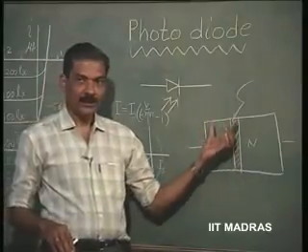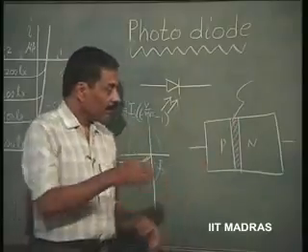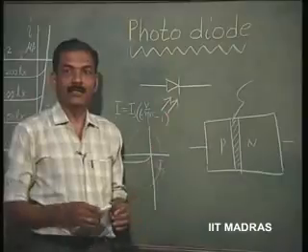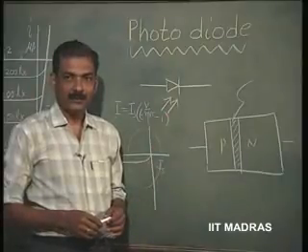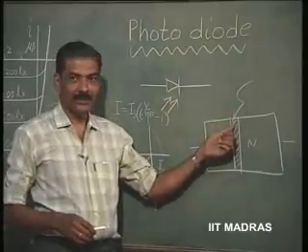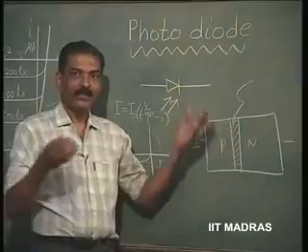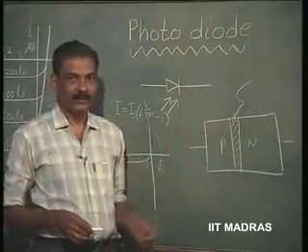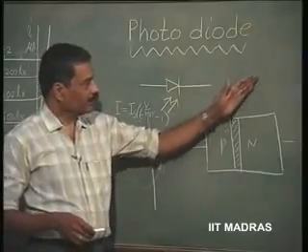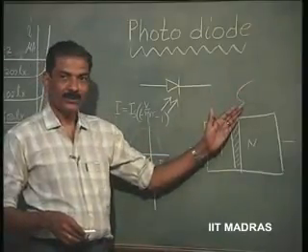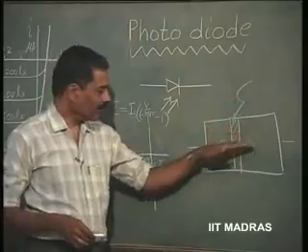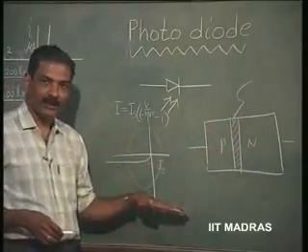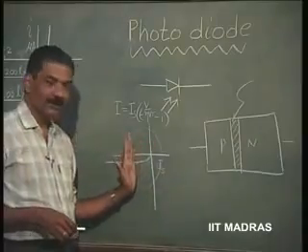Is it clear? Now, if light falls on this junction, that will create further carriers, right. This will give enough energy here to break bonds and create free carriers. So, the carriers here will increase. So, this energy is a source for creating more carriers. So, that means more current, such reverse saturation current can be sustained, for the same reverse voltage.